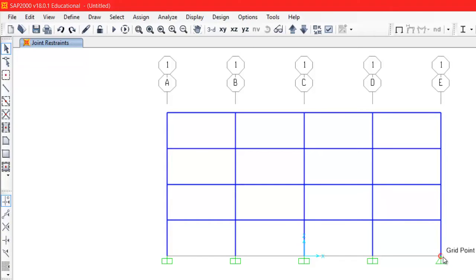Here for this one, for the grid, for the leaning column, this is hinged, that's fine. So I leave it like this. Then let's go again, since we are still talking about boundary conditions. If I look at this bay, I need those things to be truss elements. If I look here, all those members are connected as fixed connections. So if I need them to be hinged connections, or a plastic hinge, pretty much 0 rotation, then I will need to introduce those hinges here for the columns and the rigid links, both.